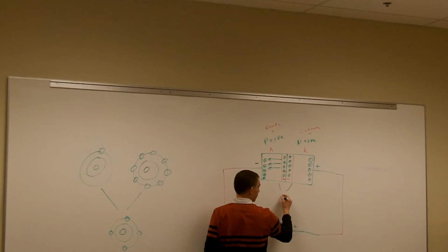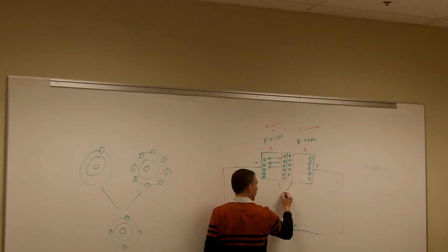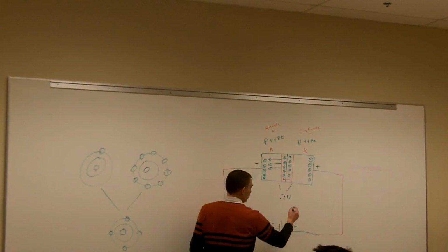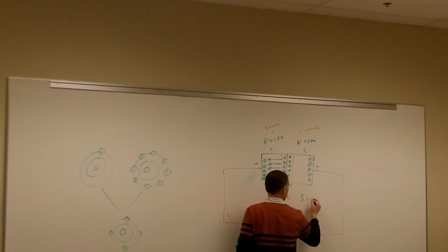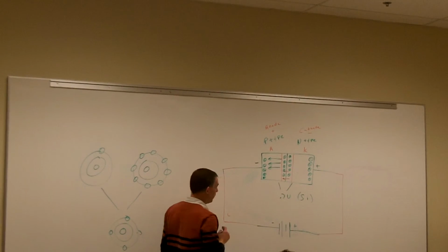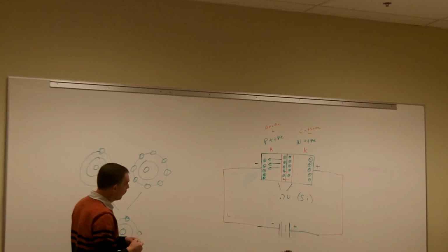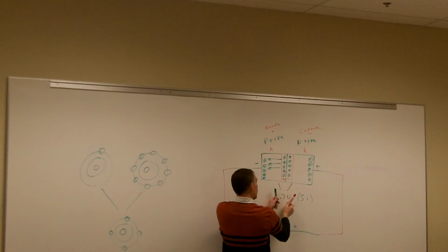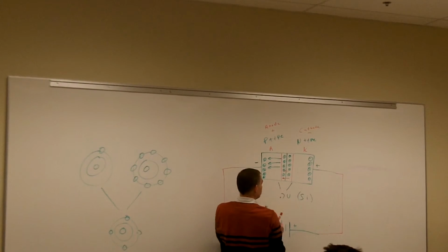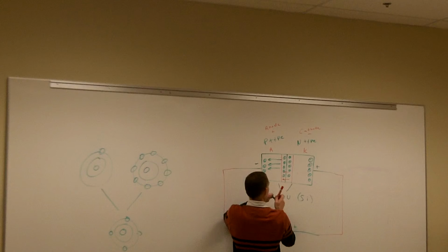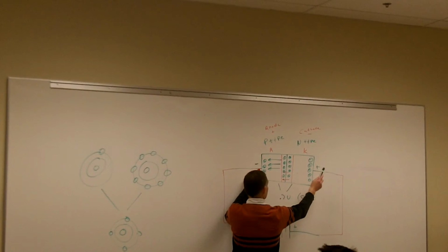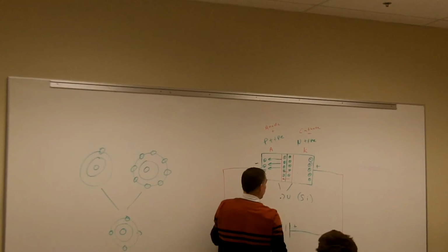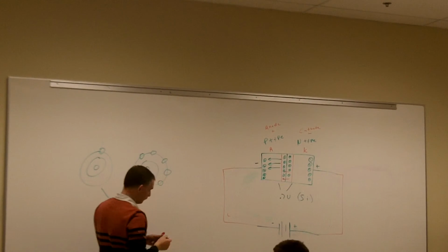And that voltage on a silicon one, for theoretical purposes, is going to be 0.7 volts. So silicon is always going to be 0.7 volts to jump that barrier potential. Once that electron starts to flow, I'm always going to drop 0.7 volts across that. So if I take my meter and I put my red lead here, my black lead here, and I measure my voltage, I'm going to measure 0.7 volts across that diode.